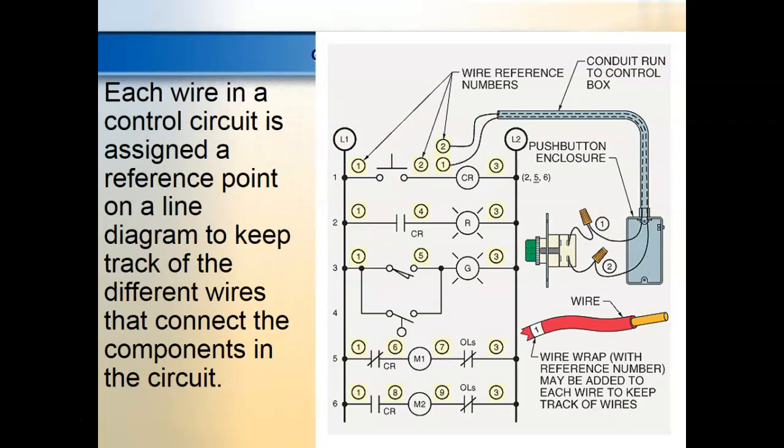These are what we call manufacturer's numbers. These are not, these are wire reference numbers we're looking at right here. So what we do is we number wires, and while we number wires, it gives us the ability to hook them up. On airplanes we worked in, every wire was white wire. What they would do on the jacket of the wire, every 6 inches, they would have a wire number on it. So no matter where we was at, we could find that wire.